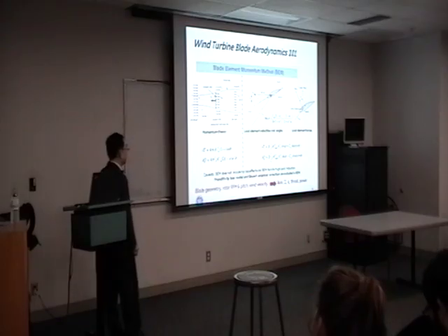The fundamental idea is simple. If we know the blade geometry, rotor RPM, pitch angle, and wind velocity, we can compute angle of attack, CL, axial induction, thrust, and power.